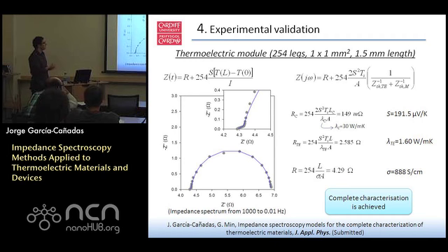So from the fitting, I have all the parameters, and using the thermal conductivity of my ceramic from the resistance of the contact, which is this value, I can work out the Seebeck coefficient. And then now if I know the Seebeck coefficient, I can calculate thermal conductivity and also electrical conductivity, which again in the module is a bit smaller because of other contributions.